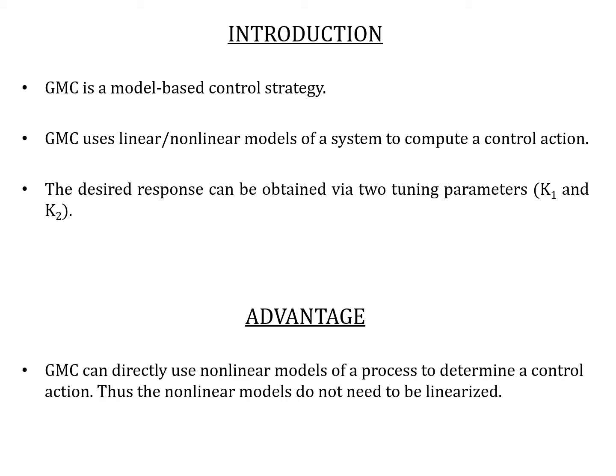And again, linearization may not be so simple for a complex system. It may be very difficult to achieve, very difficult to get accurate parameters, and very difficult to get it to work on a bigger range of control action, a bigger range of operating regions.